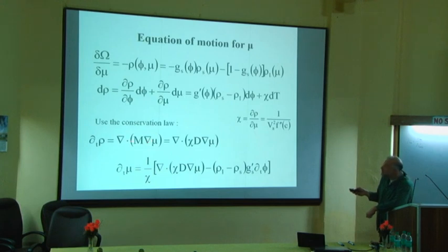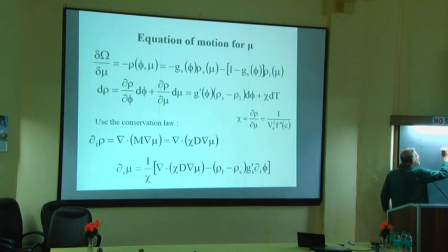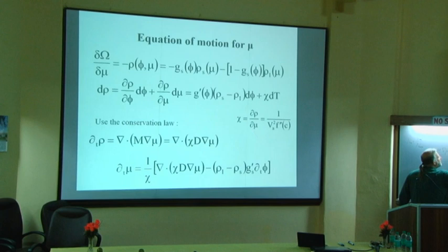And now I can use precisely that the mobility can be written as the product of this inverse of the thermodynamic factor and the diffusion coefficient. Actually, we have seen this yesterday as a calculation on the blackboard. I have told you that minus m grad mu could be written as minus m times d mu by dc grad c by using the chain rule, and you see that this is equal to the diffusion coefficient.